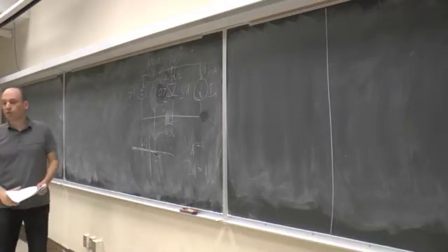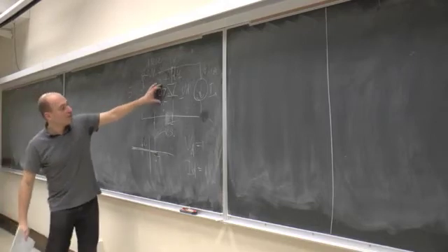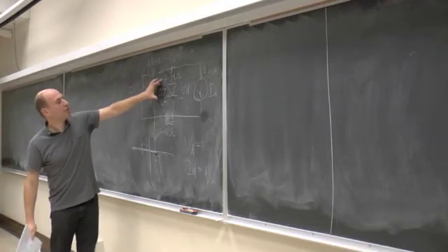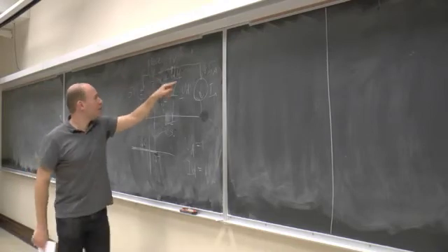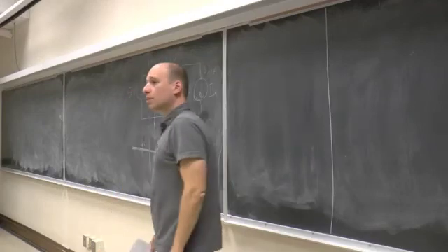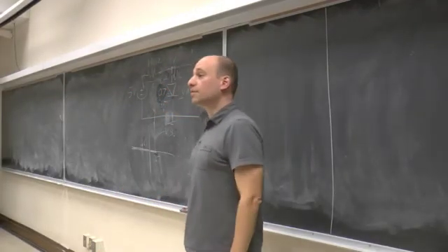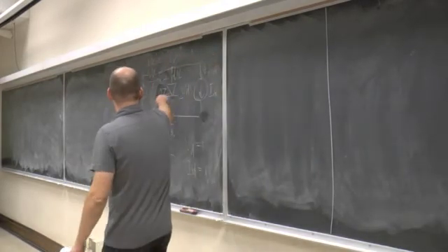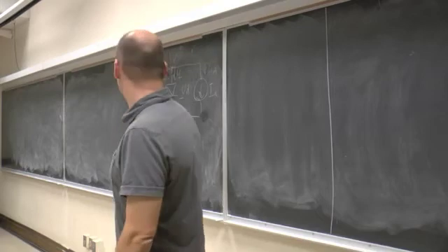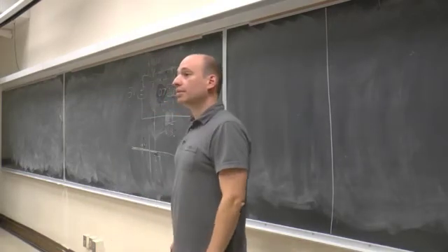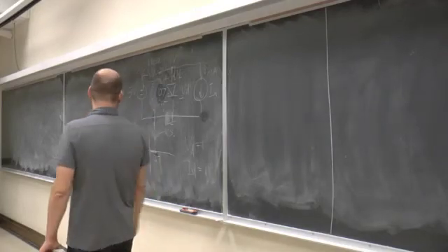Wait a second, we've just come to a contradiction, right? I just wrote 0.7 volts across the diode, and I'm going from ground across the diode, there's nothing else above it. But then I also wrote 1 volt. Which one's right? Let's vote on it. How many of you think the 0.7 volts at this node is correct? How many of you think 1 volt is correct? Okay, about 50-50, of those that voted.